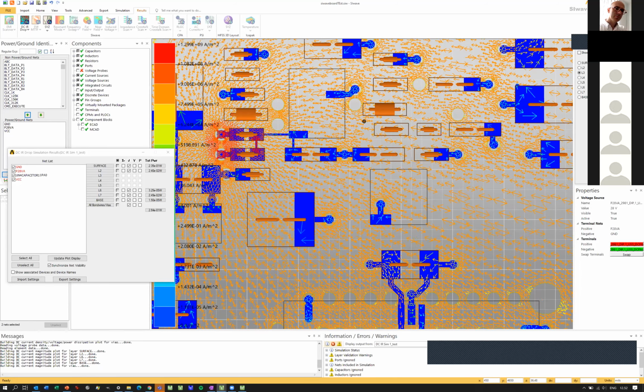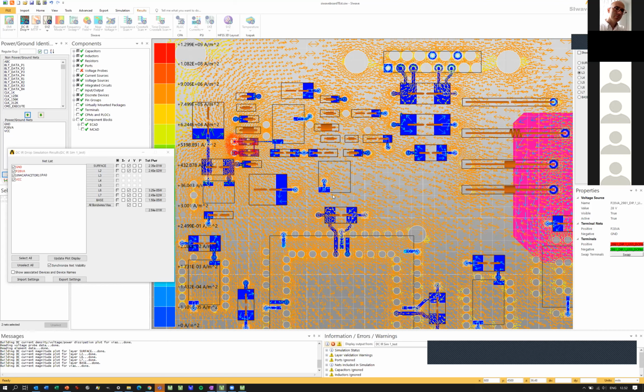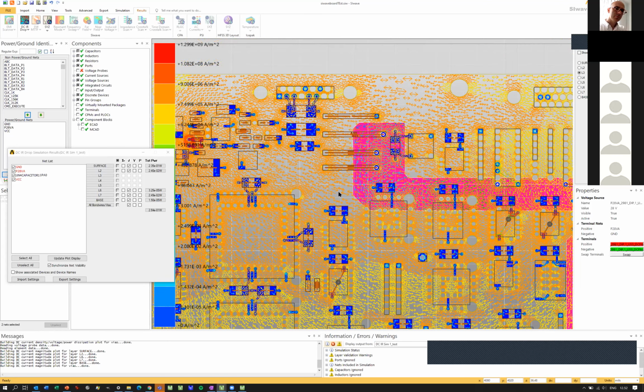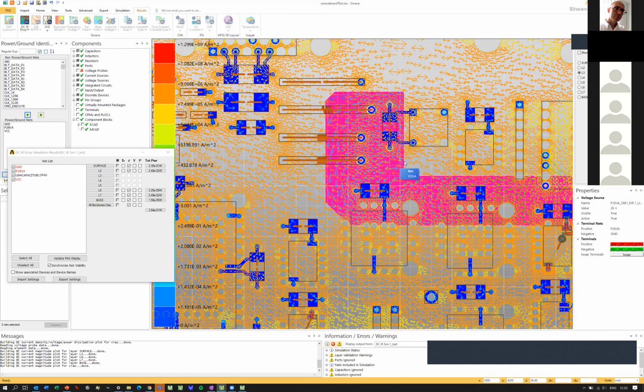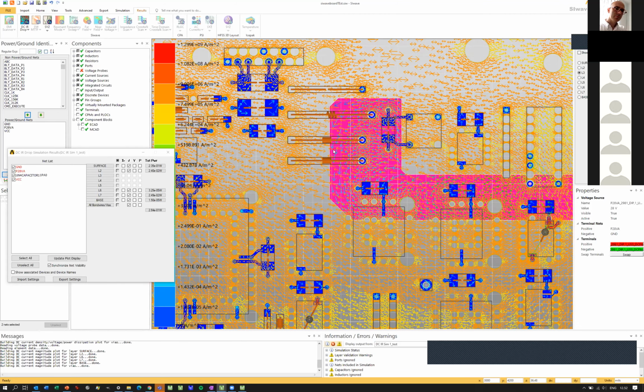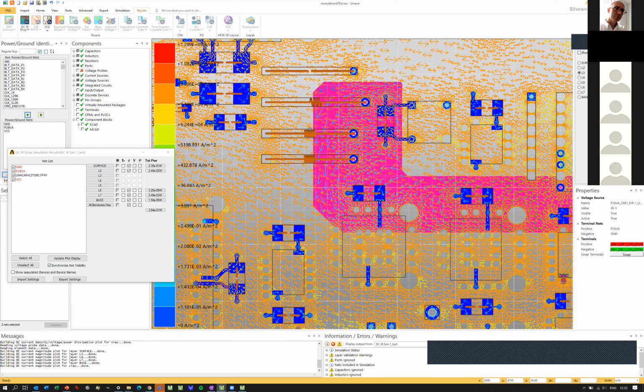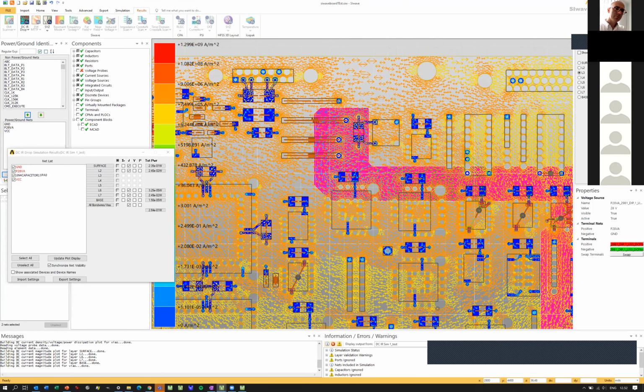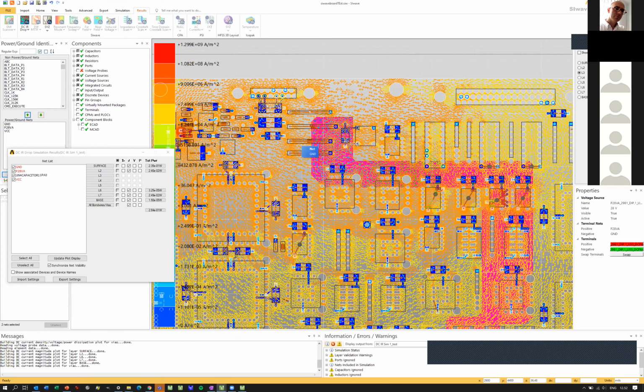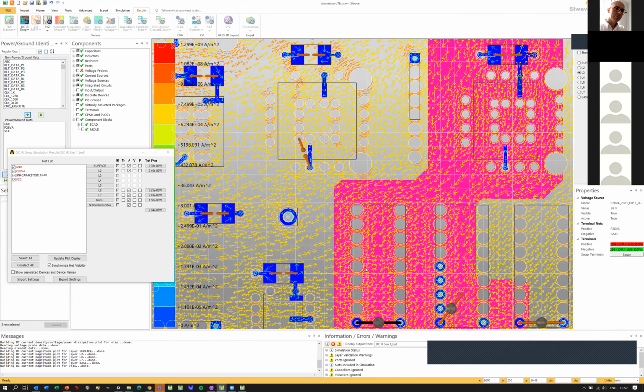And this is the reason why we have a wide power, not a trace but a plane, splitting the power to a wider area, so it's not heating up too much, and so on. Here we can see it's feeding these components. Oh, sorry, this is the source.